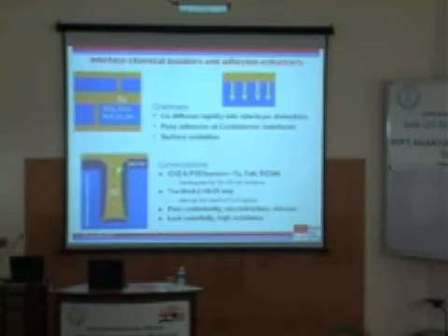So I'm compromising the area that I need for low resistivity copper. So ideally, I'd like to have this as thin as possible. The diffusion barrier should be as thin as possible to isolate as well as provide integrity.